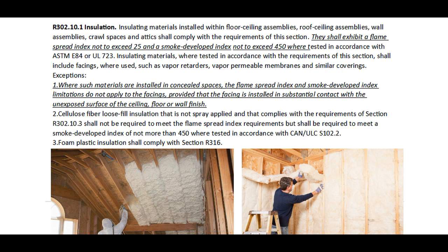Exceptions. Where such materials are installed in concealed spaces, the flame spread index and smoke developed index limitations do not apply to the facings, provided that the facing is installed in substantial contact with the unexposed surface of the ceiling, floor, or wall finish.